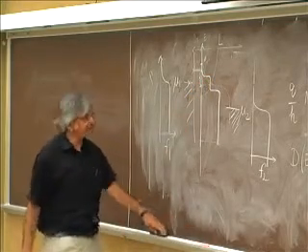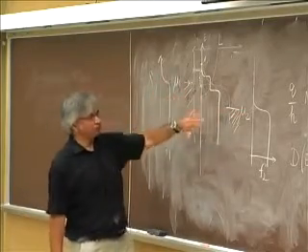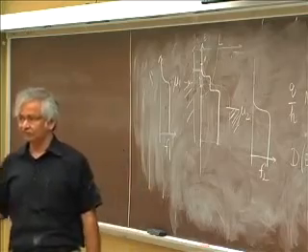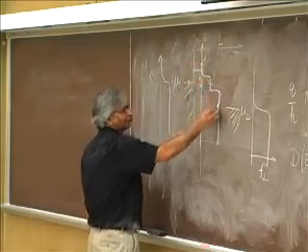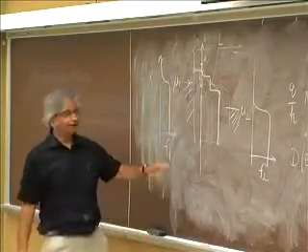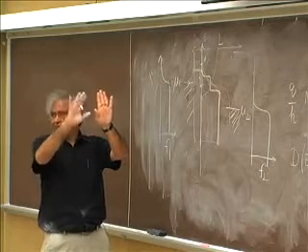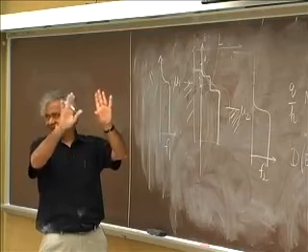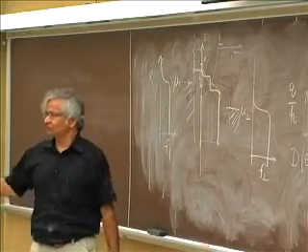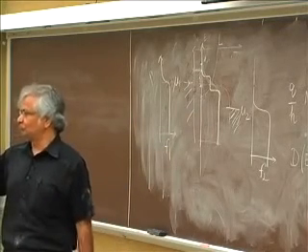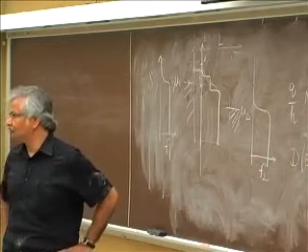But one interesting point is that if the amount of voltage involved, this mu1 and mu2, if that difference is much less than kT, then actually it wouldn't look like this. It would actually automatically look almost like a Fermi function anyway. You can take two Fermi functions which are just a little bit off, less than kT, and add them up. It looks almost like a Fermi function. That's this Taylor series idea. Then even without scattering, it's almost a Fermi function, which means if you, after that you put in some scattering, it won't really do much to it, because it basically is trying to restore a Fermi function. If that's already there, it won't.